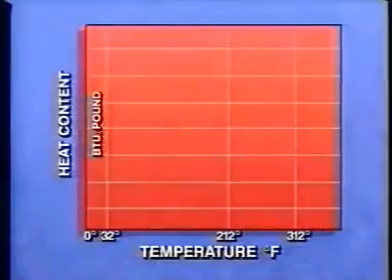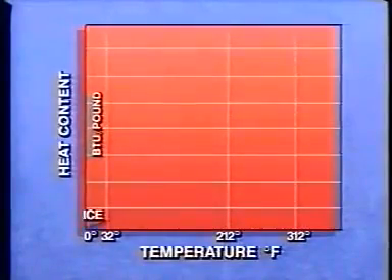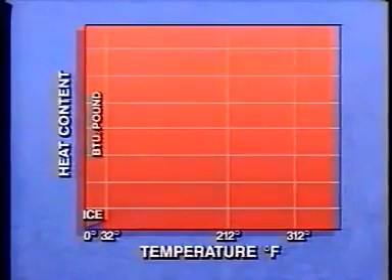There are 2 types of heat. One is sensible heat. It can be sensed or registered on a thermometer. The second type is called latent heat. Latent heat affects phase and is hidden from the thermometer. The following graph will show what this means. The solid phase of water absorbs 1 BTU as its temperature increases 2 degrees. If the temperature increases from 0 degrees Fahrenheit to 32 degrees Fahrenheit, it has absorbed sensible heat, since the thermometer records an increase.